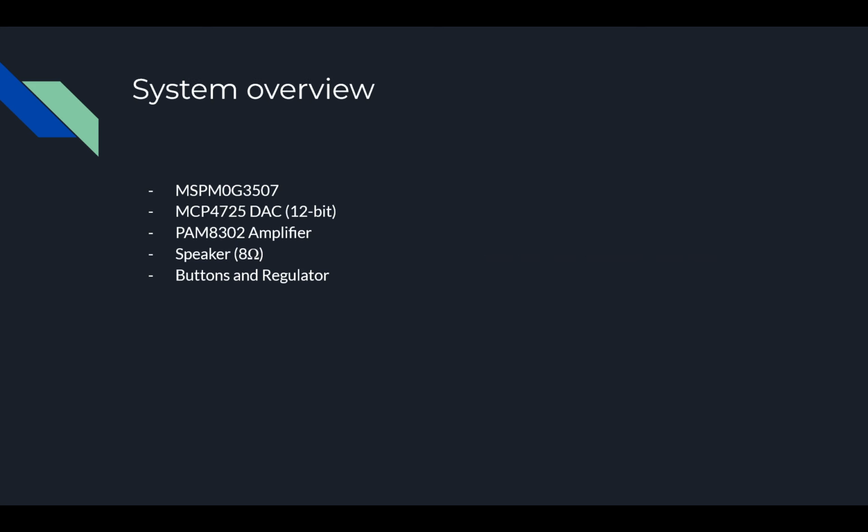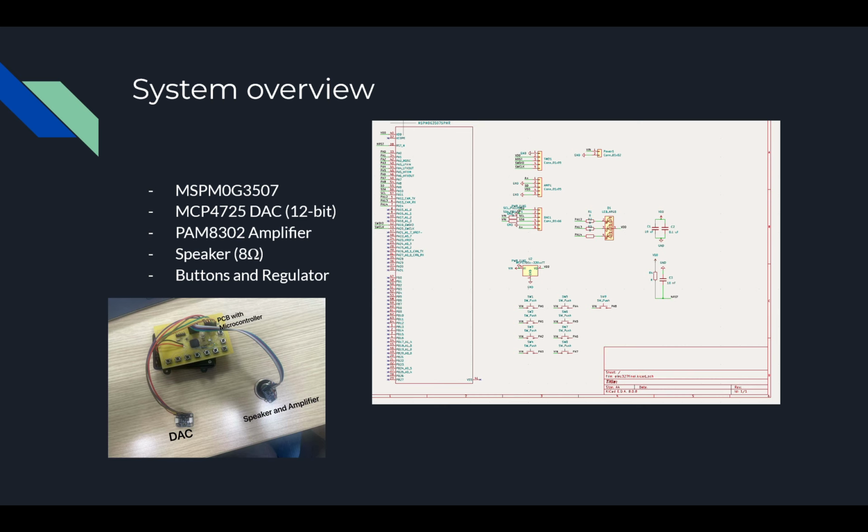The system is built around the MSPM0 microcontroller. We used I2C protocol to communicate between the microcontroller and the DAC module. The microcontroller sends computed digital waves to the DAC. The DAC then outputs an analog voltage waveform to the amplifier to amplify the audio.